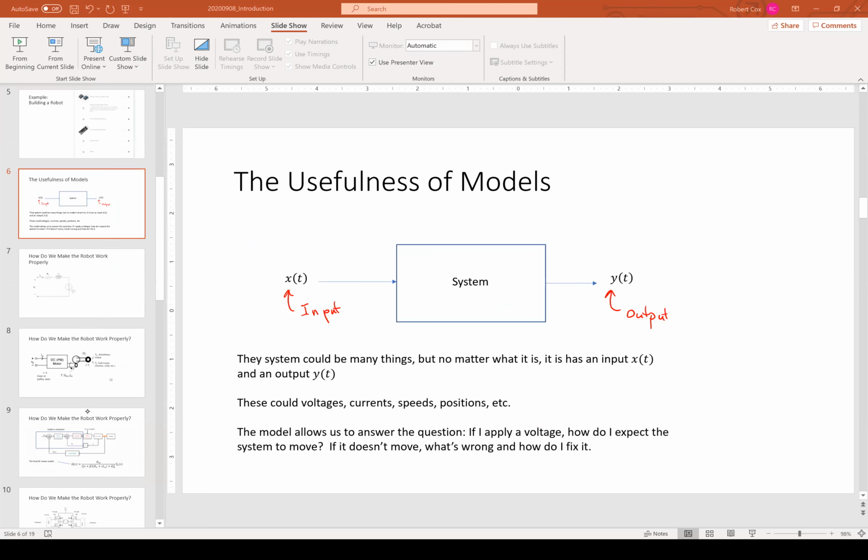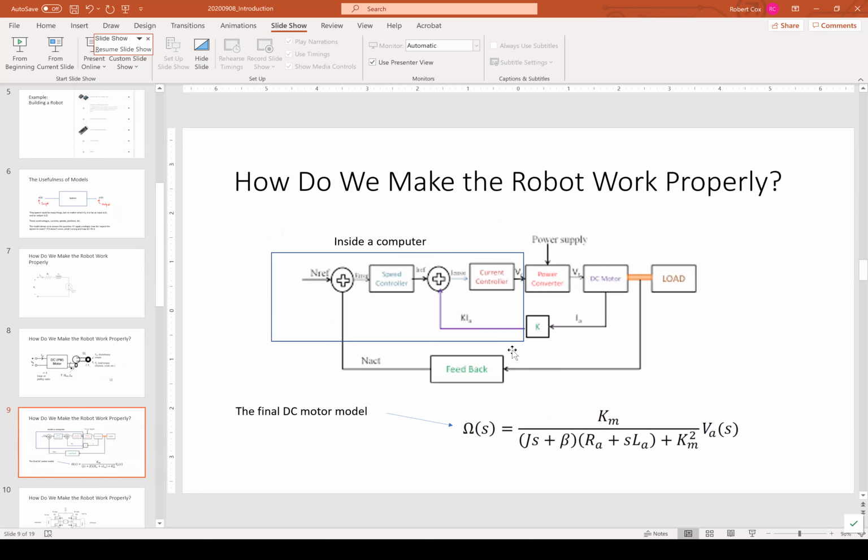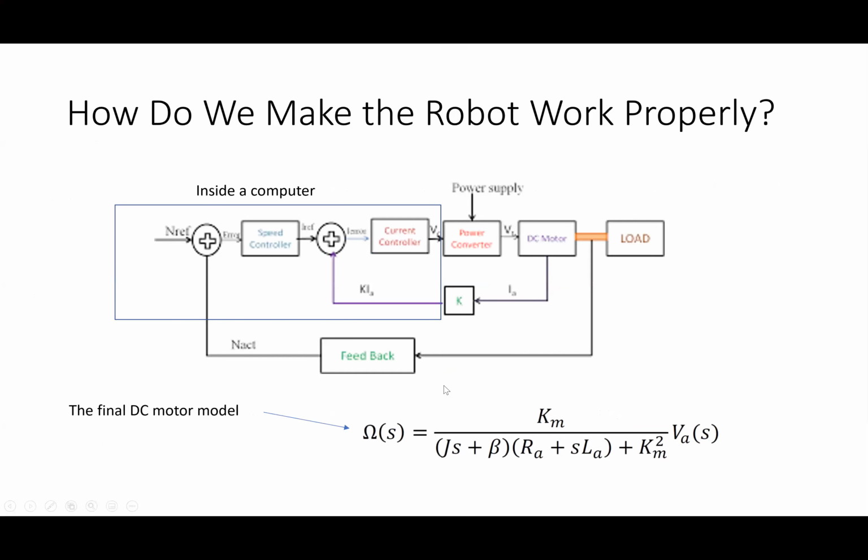That's right. Now, I don't expect you to fully remember that, but you should have seen the Laplace transform in differential equations, right? That Laplace transform is actually a useful tool because it allows me to develop this model that tells me ultimately how a motor's speed is going to respond to a particular voltage that I put in there. And that allows me to go into a computer and write the code that I need to properly get this motor to do what I want it to do. And when it doesn't do what I wanted it to do, I have a model that I can go back to and think about to figure out how I need to tweak and change the code.